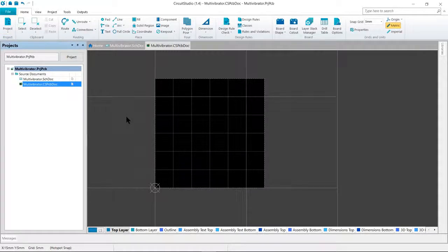Now, when you run this command, the design is compiled and a set of engineering change orders is created, which will list all the components used in the design, the footprint required for each. When the ECOs are executed, the software will attempt to locate each footprint in the currently available libraries or available content vault and place each into the PCB workspace. If the footprint is not available, an error will occur.